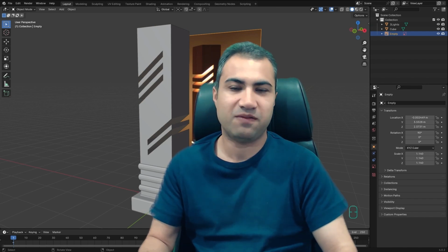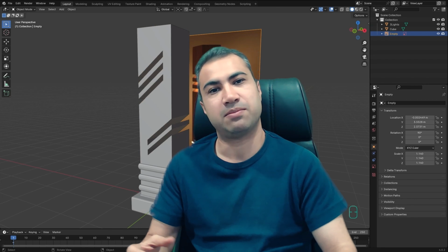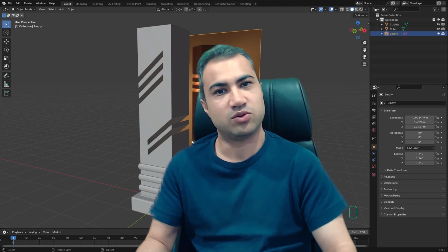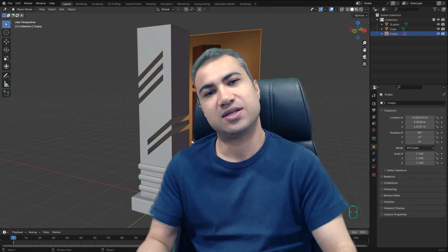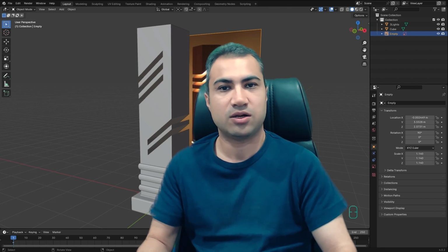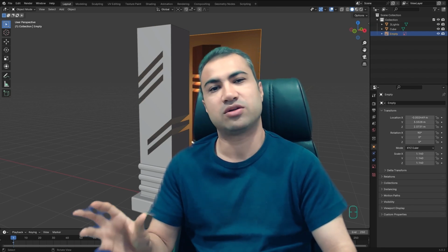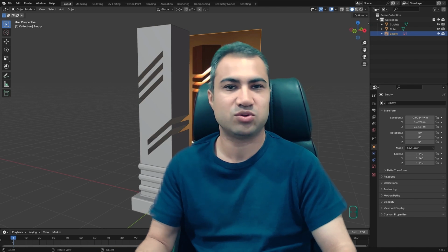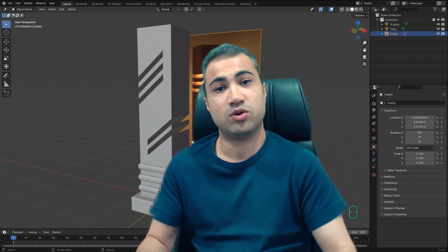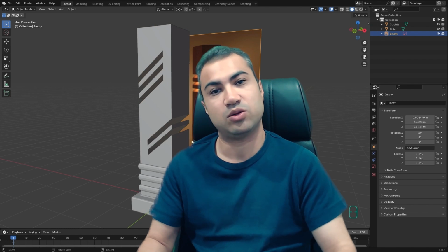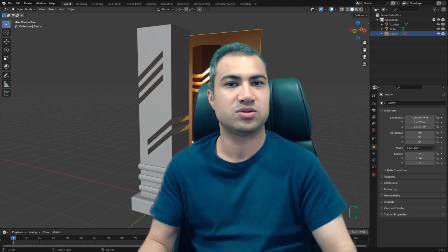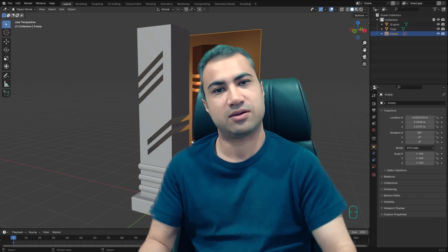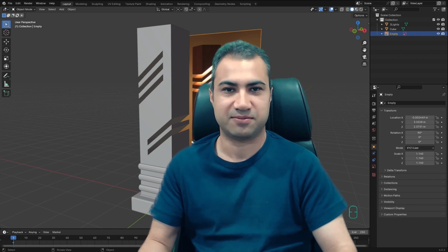Wow, this video takes more than what I thought, but I just want to mention that most of the settings in the bevel modifier are the same as the manual bevel that we used in previous videos. And my suggestion for using the bevel is that whenever you want to add an edge on some part of your object, it's better to just use the simple manual bevel. But if your object is complicated and you want to use the bevel on the whole object, it's better to use the bevel modifier for efficient modeling.